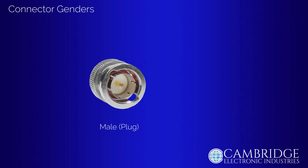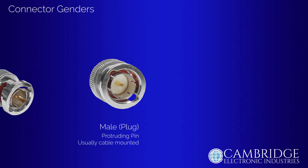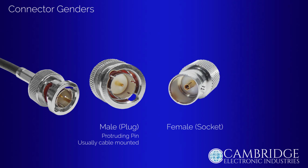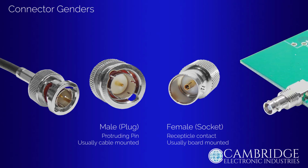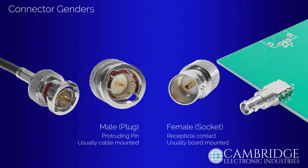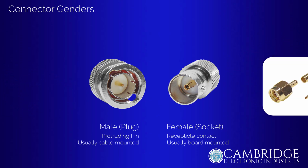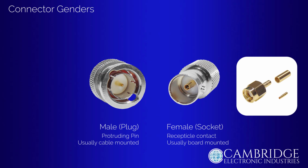Male connectors, also known as plugs, contain a protruding pin as the center contact. They are most commonly cable mounted for connecting to equipment, but some PCB mounting forms do exist. Female connectors, also known as sockets or jacks, contain a receptacle contact where the center contact has a hole or spring fingers. Usually board mounted, so equipment has sockets for users to connect to. They are also available as cable mounted jacks when required. The gender is defined by the centre contact, not by the outer shell, which can sometimes be misleading in connectors such as the SMA versus a reverse polarity SMA.